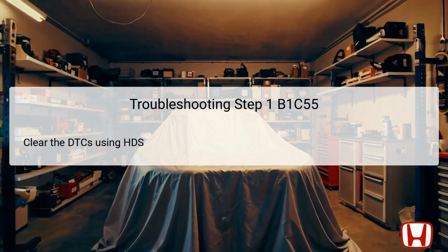The first step in troubleshooting the DTC B1C55 is to clear the stored diagnostic trouble codes (DTCs) using the Honda Diagnostic System, referred to as HDS. This procedure resets the vehicle's computer system and enables you to run tests again without previous codes interfering. Clearing the DTCs is crucial as it allows you to start fresh, ensuring that the subsequent diagnostic checks are accurate and based on real-time data.